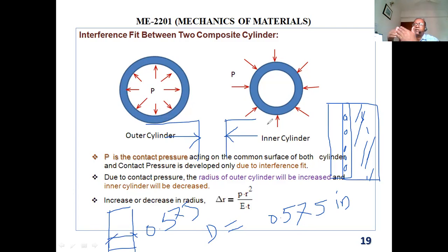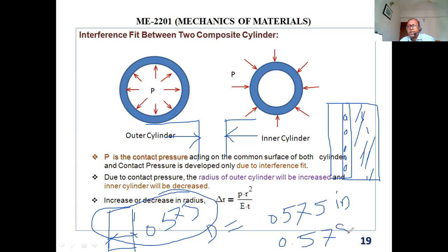Then what will happen? It will fit, but it will be a transition fit. That means the rivet will be rubbing around the wall of the hole and this rivet surface. It might develop cracks. The skin panel will vibrate. So you need to stop it. How can we do it? You cannot make the hole smaller, obviously not. So how to do this with the rivet? You need to make it a little bit oversize. So you make the rivet 0.78 inch.